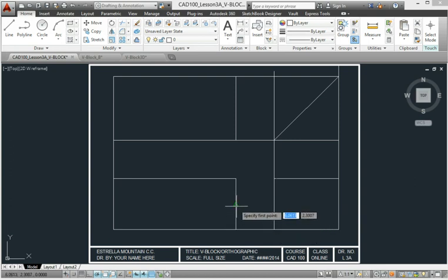Let's start with the fact that the step here is 1. We could just grab this midpoint, which happens to be half of the height of 2, and pull it to the side and type in 7/8, and then grab the perpendicular of the top of the front view. Repeat that on the other side. Snap to midpoint, type in 7/8, come up, enter. We have 2 lines that are 1 and 15/16 from either side.